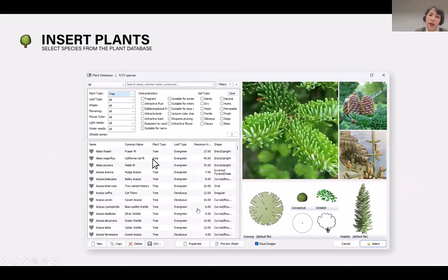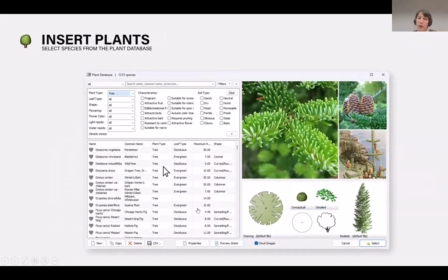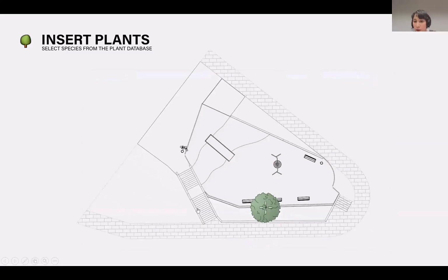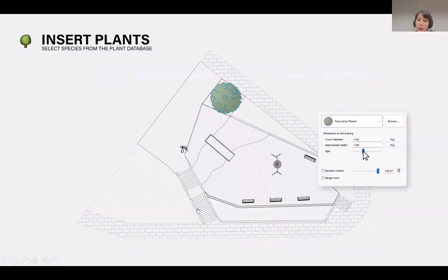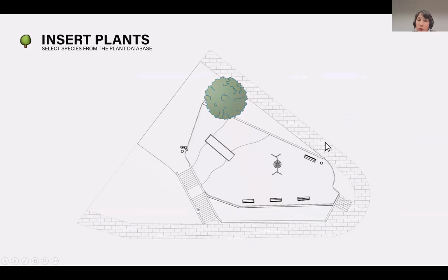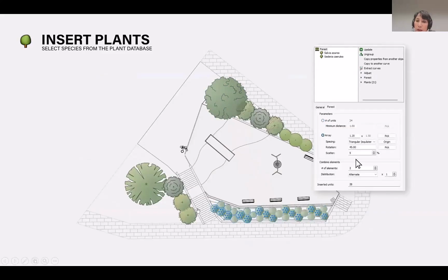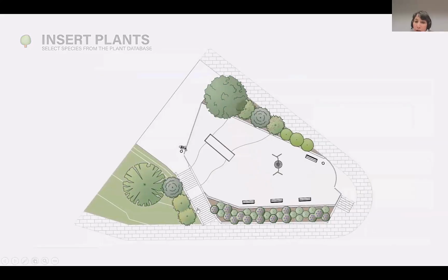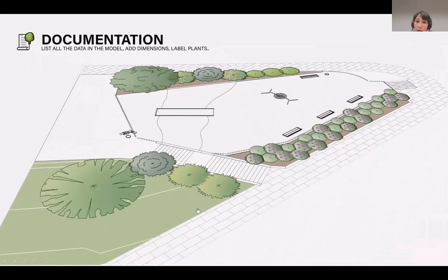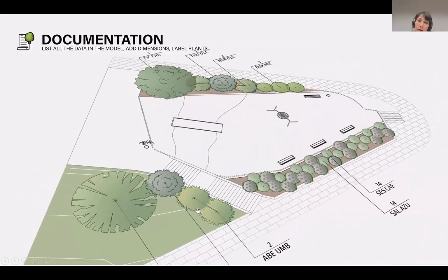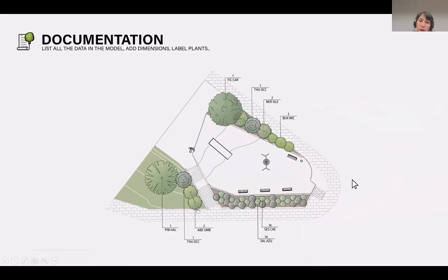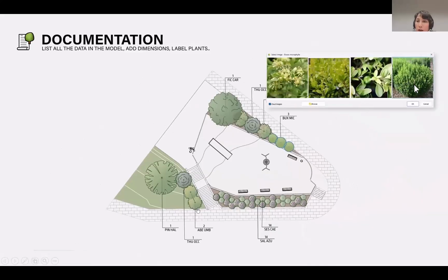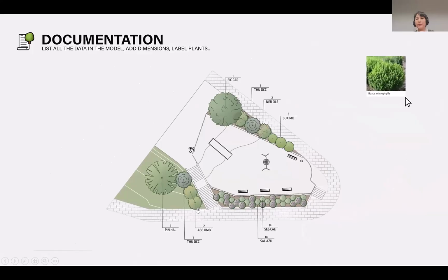So continuing, we add vegetation. As you see, we use the block library for inserting different vegetation, and the plants have their own 2D blocks. There are specific 2D symbols for any plant species. You can change the arrangement of plants, use an array system or a matrix of plants, indicating the distance and so on. You can add the label to plant species. And in this way, you produce drawings and different layouts.